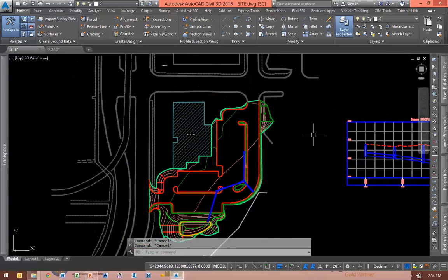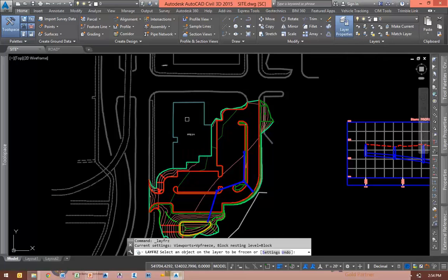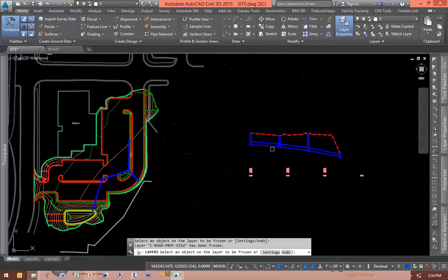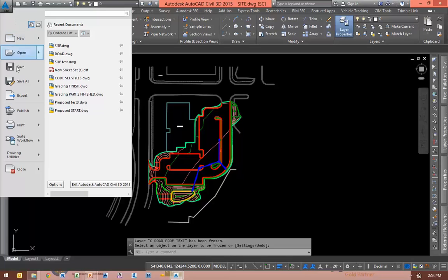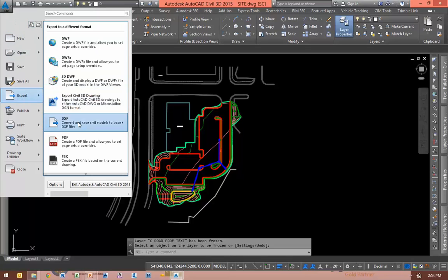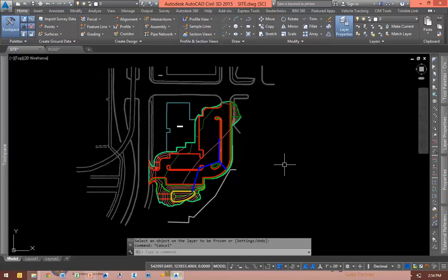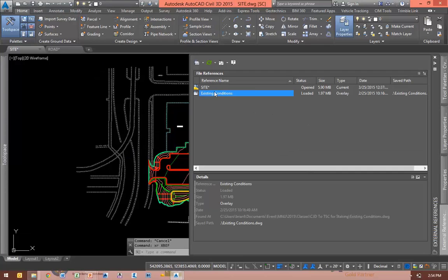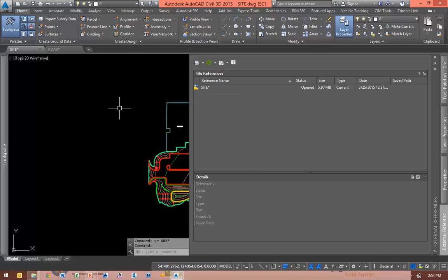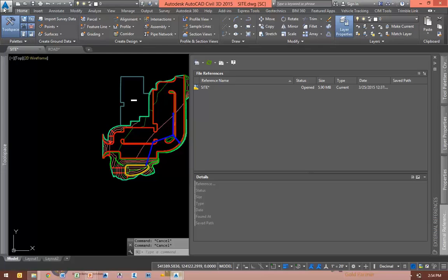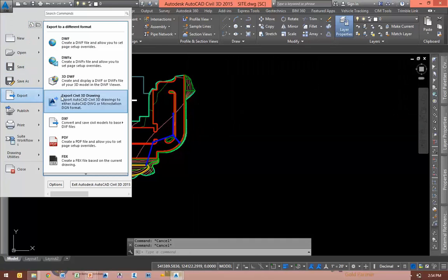So one of the things you want to do is to try to turn things off, like freezing things that aren't relevant in the data collector. But even so, and I'm going to do this here, I'm going to export to DXF. When you do this, there are other catches. You can't just freeze a few things. For example, XREFs. It doesn't want to routinely, out of the box, push out a DWG with an XREF loaded. You have to detach an XREF, okay? So for those of you who haven't done this much, let me just push this out.